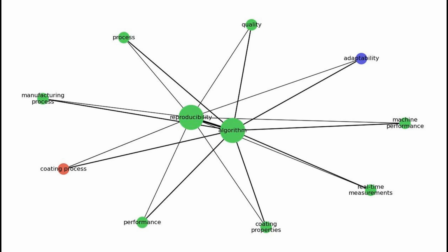For instance, while spraying a coating, the algorithm looks at real-time data, such as the measured voltage from the spray gun, which reflects how well the machine is operating. If the voltage indicates a problem, like wear on the machine parts, the algorithm can quickly adjust the spraying parameters to compensate for this issue.